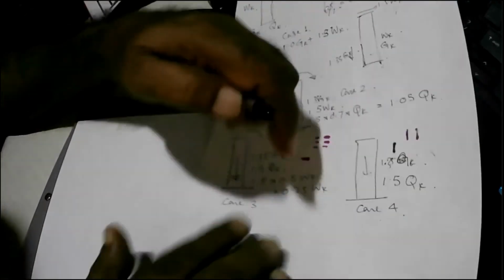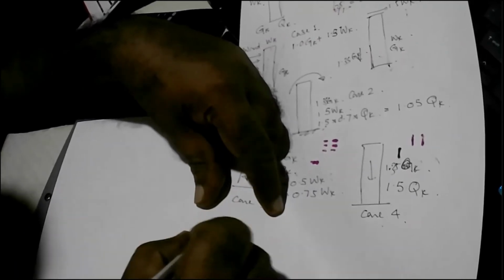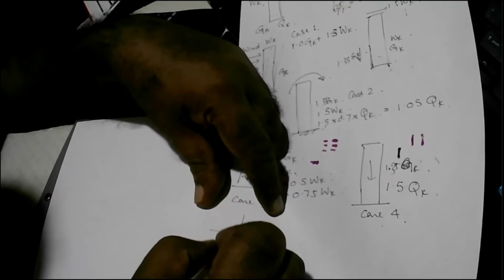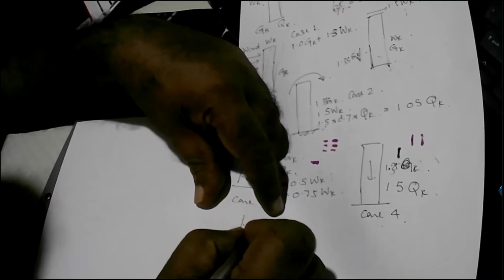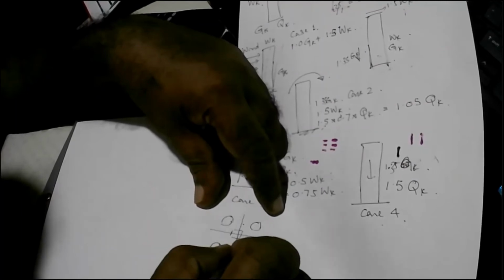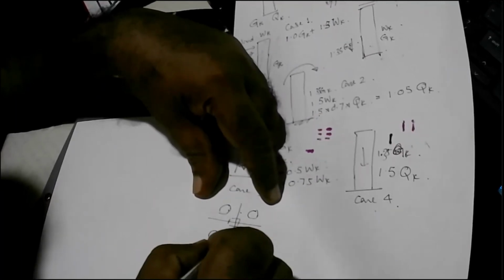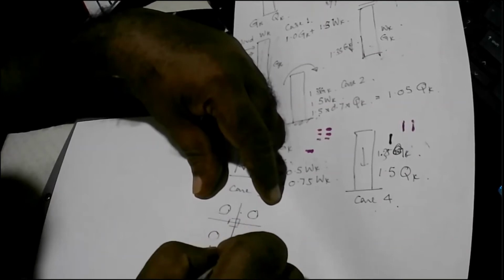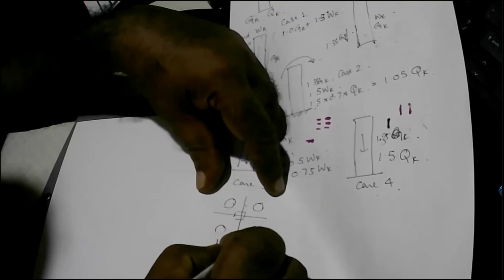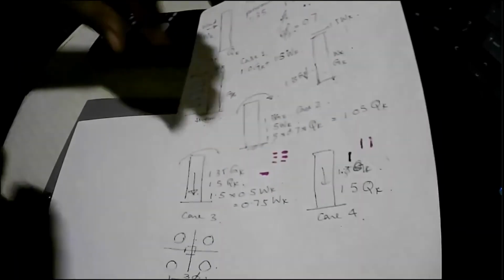If you are having 1000 diameter piles, then when you have the column, we can have the piles located like this. And the distance between the piles will be 3 times diameters. Sometimes, we go for 2.5 times diameters as well.